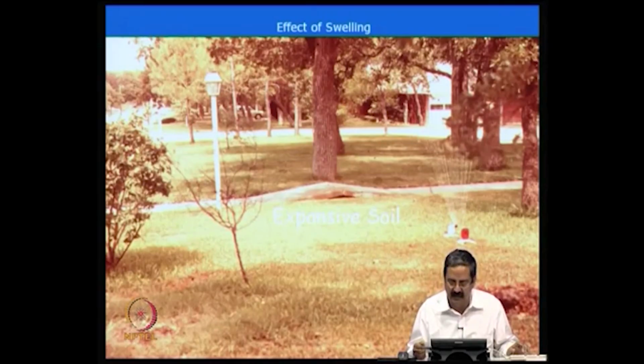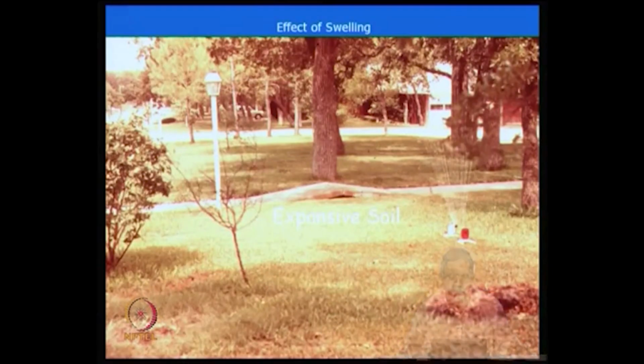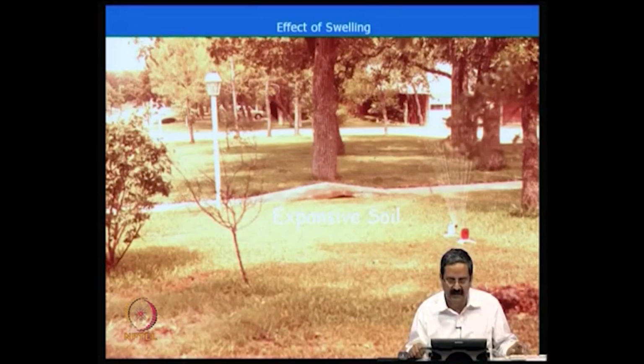Like you can see an example where you have a small mound here, in the form of a projection. So, one can see that this is all right in a small place, but you have a lot of problems with these expansive soils in India, where people are not able to construct small structures, because the problem is the swell pressure that is associated with that.